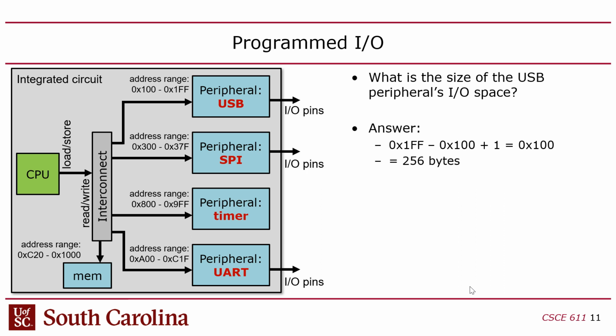It has all the ranges in it. So if you wanted to build an FPGA platform like in 3.13 and run Linux on it, you would have to create a custom device tree with all of these address mappings stored in there, so Linux drivers would know how to connect to those peripherals. That's all communicated through the device tree.